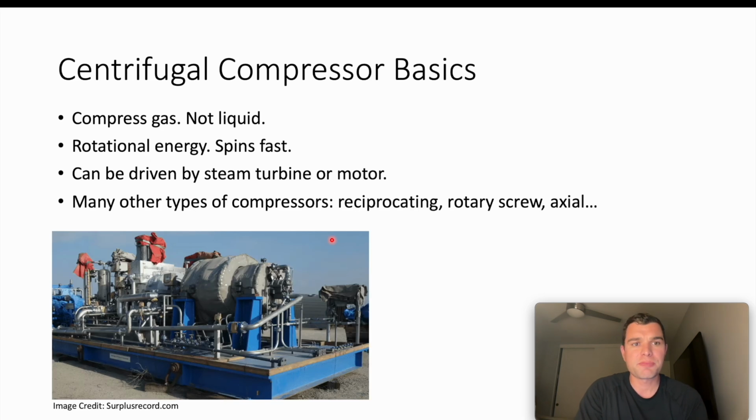Centrifugal compressors compress gas, not liquid. Liquid is incompressible, or is at least assumed to be. Compressors have rotational energy, they spin fast, and that's essentially how they make dynamic head, essentially moving gas from one place to the other, or the potential to do so. They can be driven by a steam turbine or a motor, which would be by electricity.